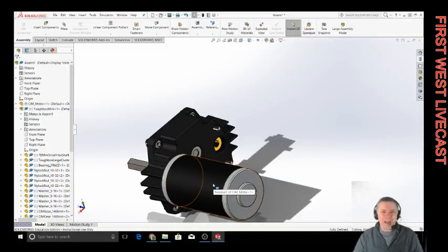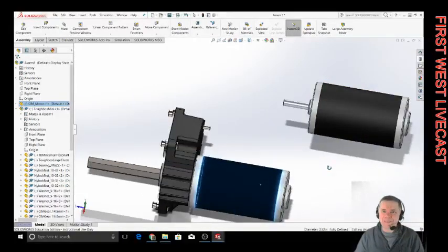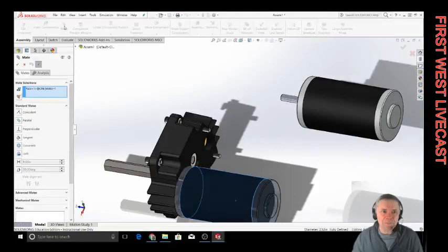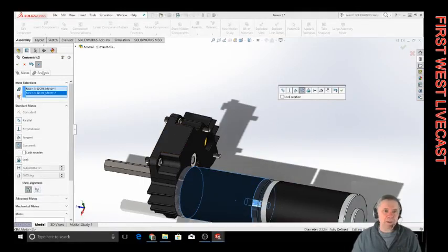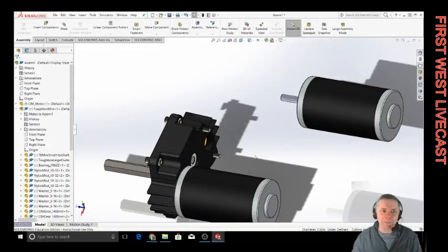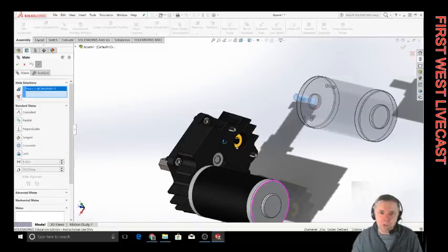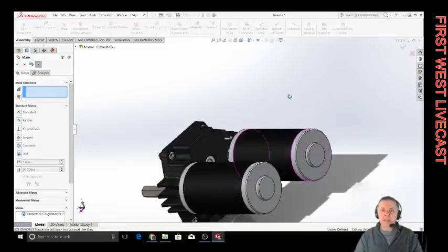All right, so I hold the control key down, and I'm going to click on the motor and drag with the control key, and voila, I have a second motor. It's way easier than having to order anything from Andy Marks or Studica. Just the control key and drag. And again, we're going to do a mate. We're going to mate from this object. Oops, that's a very unusual mating. I don't think that's probably what I had in mind here. Let's do it again. So we go mate from this shaft to the inside of that, like that. And we say yes. And now we have 2.